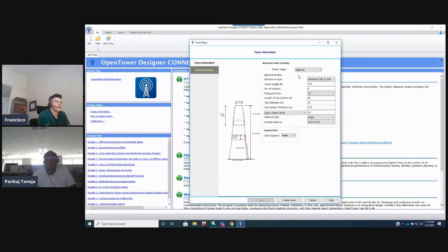And there are a lot of reasons for it too, because I think the industry has done a lot of research on this. Like, we say you have round poles and then you have polygonal poles, right? You take the plate, bend it into multiple sides, seam weld it, and prepare a pole. There is a reason behind why we do that, right? Because the stiffness of the plate is definitely higher, and when you make it a polygon, it's pretty stiff as compared to the round pole section.